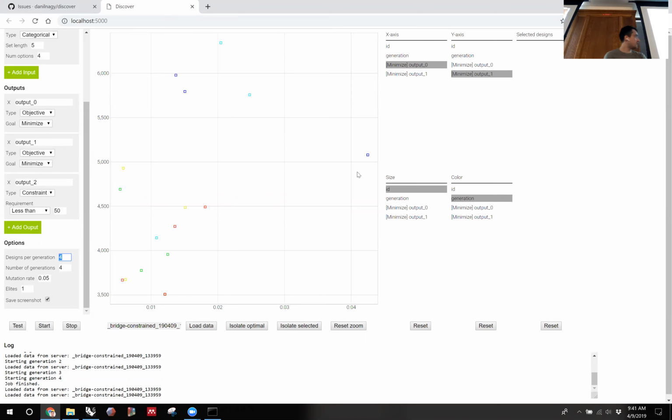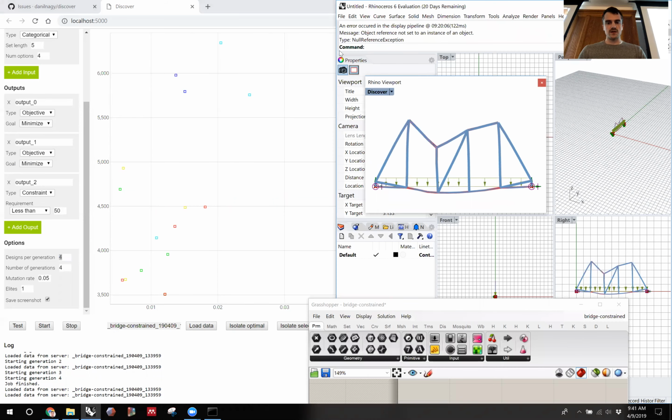This is typical, and at this point, we have to decide whether our model is over-constrained. Because it could be that the model is set up in a way that it's impossible to meet that constraint. We don't know. If we're dealing with a real-world problem, like a structures problem, that would be really important, right? We wouldn't want to adjust the constraint if we're really looking for that safety factor. We would need to change the model somehow, increase the size of the beams, or something like that. So let's try that really quick.